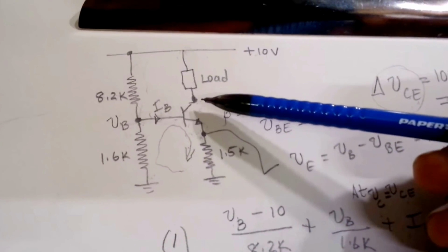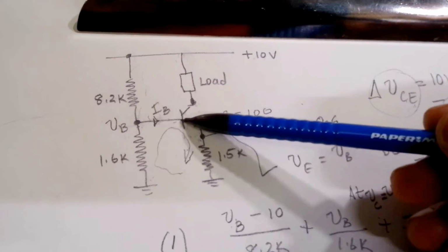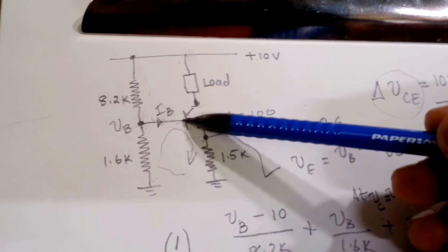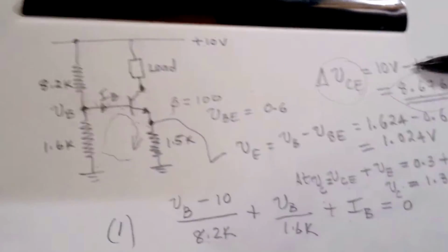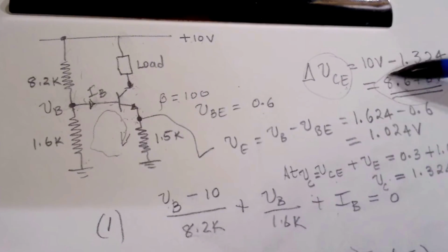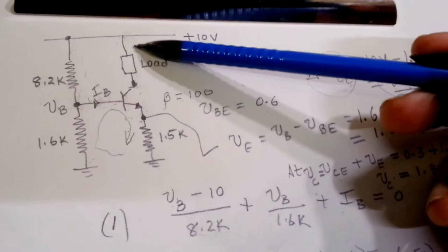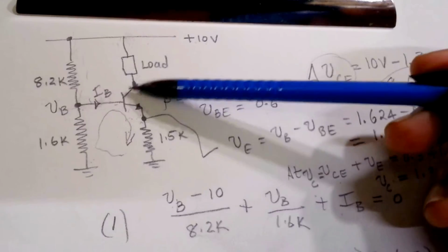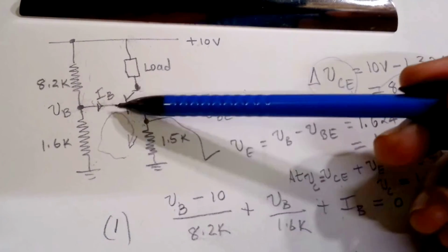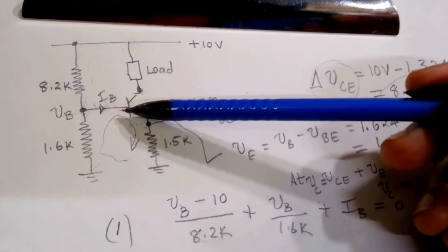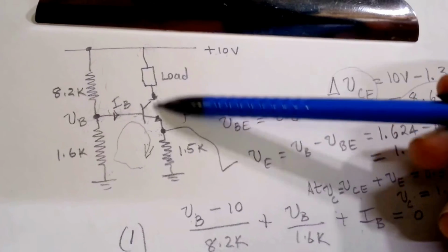The other effect is the variation in the collector to base voltage, because when the output compliance is from 0 to 6.7 volts and you change the load within that range, the collector to base junction voltage is not going to remain the same. So that will also affect the current that goes through here.